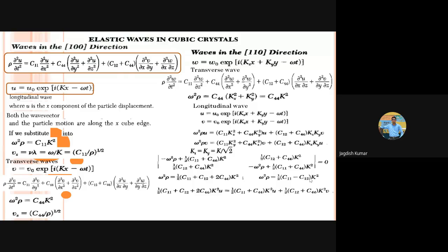Okay, first root. If we focus on the first root, then the first root describes a longitudinal wave and the second root describes a shear wave. I mean, how do we determine the direction? We will talk about what is shear wave and what is longitudinal wave. So let us first talk about the first root. Let us take this one and then substitute this into this equation.